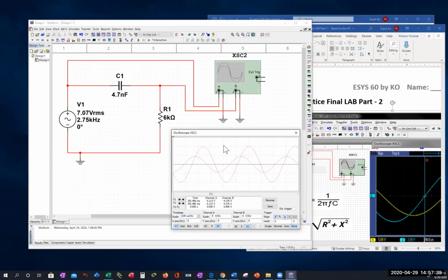I think peak to the middle would be what, 3.53? Peak would be, here's the middle line. And so the middle line we would count up to one of these. And which one of these represents 10 volts peak? The shorter one or the taller one? Which one? Why the taller one? It's 5 volts per division.